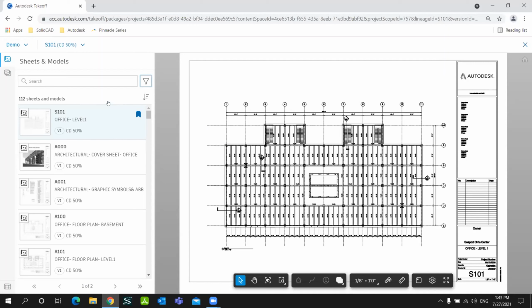So now that we are on our sheet, before moving on and showing you the takeoff types here, I would like to quickly mention that you have a set of tools over here, related to the view. Then this is the tool that you select, whether it's area, linear, or count. We'll see that in the takeoff types. We'll also see this tool, which is combine and cut out. Then you have the scale over here, where you can choose, or you can even calibrate based on the dimensions of the drawing. Then you have a quick measurement tool. And finally, you have the settings over here.